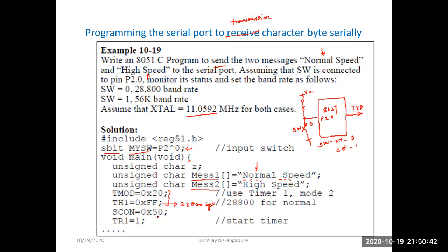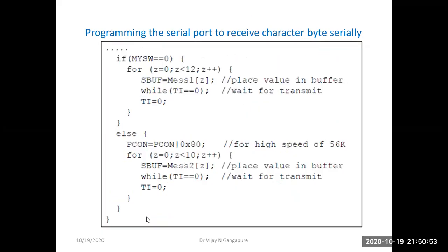Then SCON is equal to 0x50, means I am configuring the serial port of 8051 in mode 1, that is 8-bit UART mode, and then I am turning on timer 1.